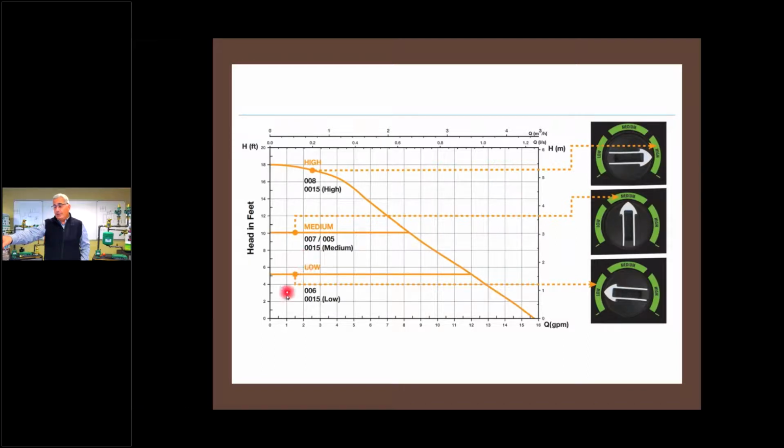But there's this thing called the system curve, and it's going to be going up this way because it has to. It's physics. We will end up performing at the 10 foot of head mark and probably overpump by 1 GPM. So there, I will be squeezing my delta, but I'm still close. Either way, I'm going to be close to where I need to be.